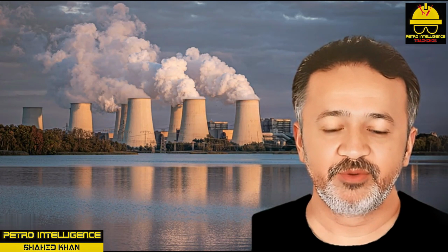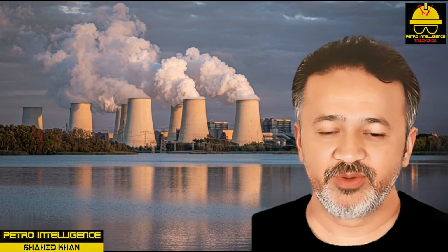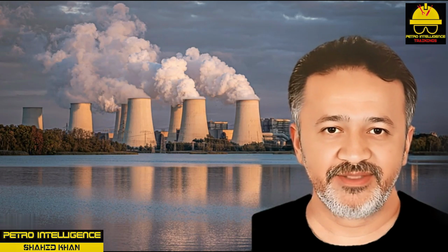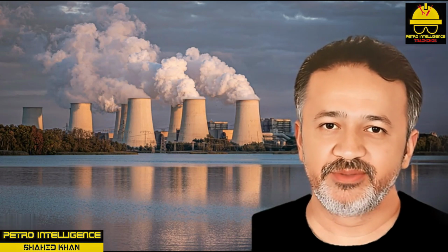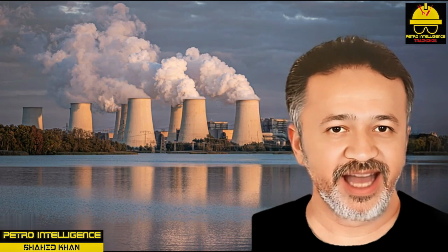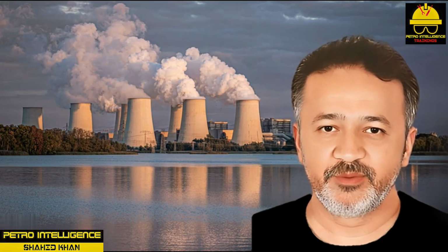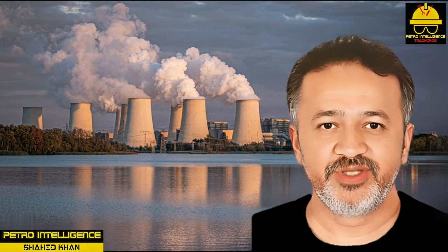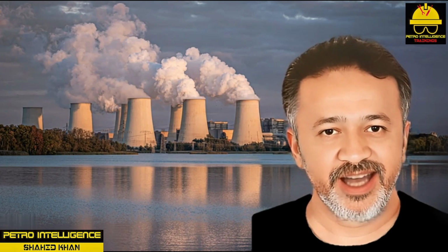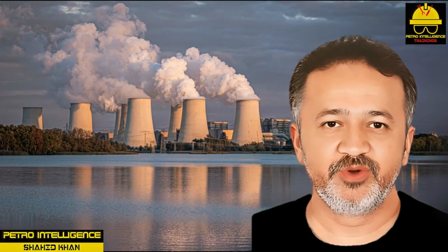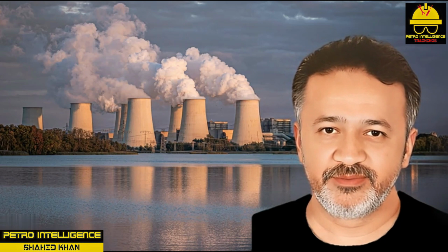Operators face the following problems when working on a cooling tower system. Suspended solids can accumulate in the water and eventually form deposits or scale. Electrochemical reactions with metal surfaces cause corrosion. Silt, debris, and algae foul and plug exchanger tubes. Fungi and bacteria cause wood decay. There are several approaches for solving each of these problems.